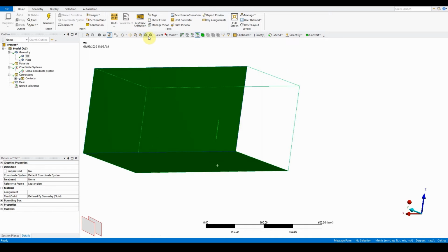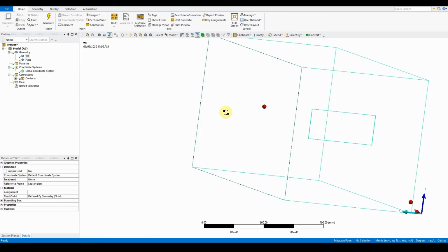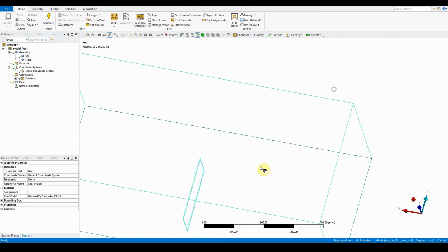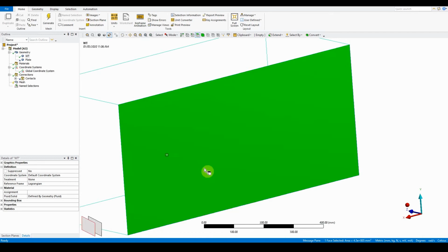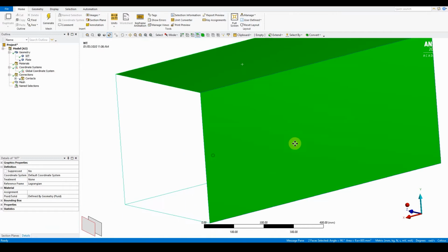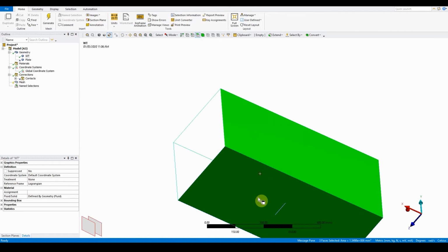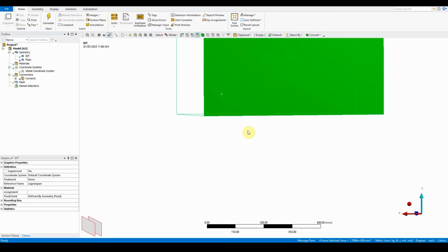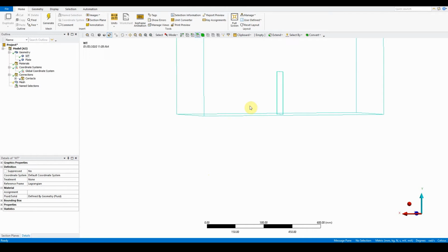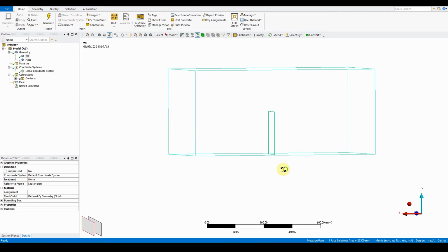Again, there should be a panning tool which can bring it back in again. And what we want to do now is grab the inner plate, and the inner plate is going to be a bit of a hard time because obviously you've got these surfaces that are in the way. So the best thing to do is grab these 4 again. And what we want to do now is press F8 on the keyboard, and it will hide those faces, meaning we have access to these.